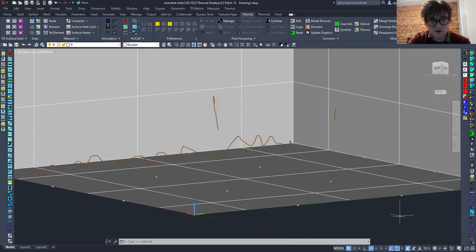basically this node, or no, that's a bad example. It's going to allow this node to talk to this node on this face. I'm saying this a lot. That's probably confusing. But does that make sense? Because right now, these things might look like they're connected to your eye, but as far as the thermal model is concerned, they don't have any connection.